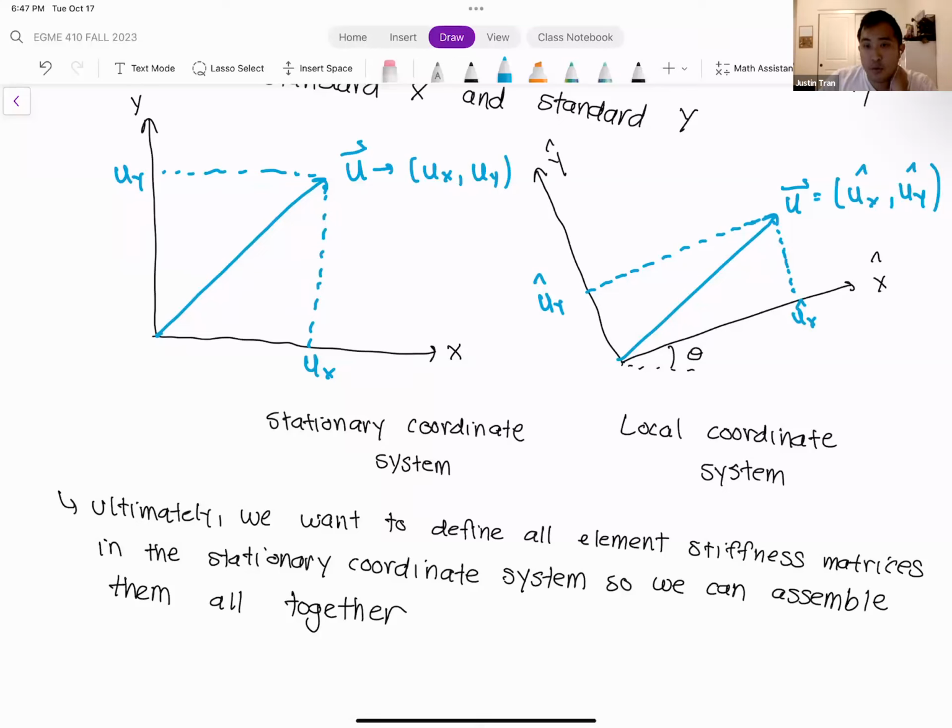So for problem 6, I want you to change the support condition. In the default configuration, we applied a fixed support on one side of the rod and a displacement support on the other side, if you follow the PDF exactly. I want you to add additional supports. Instead of supporting it from the ends of the rod, as in the PDF there, let me go ahead and share my screen so you can see.